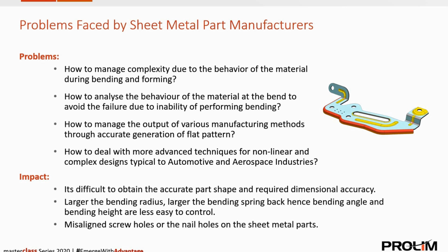Misalignment of holes is one of the known problems. The larger the bending radius, the larger the spring back. Hence, the bending angle cannot be maintained to get the accurate final output.